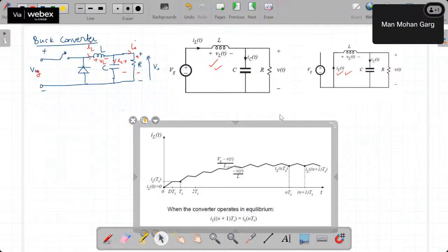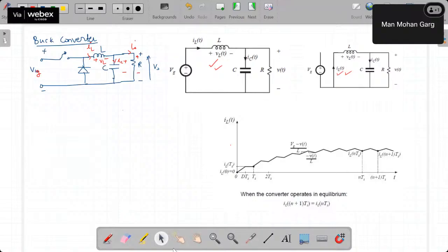But before that, we assume certain things. So assumptions. First, we are considering that all the inductors, switches, diodes, components are ideal. All the components are ideal, right? And second is that this converter is operating in CCM. Third is the switching frequency f and duty cycle is D.